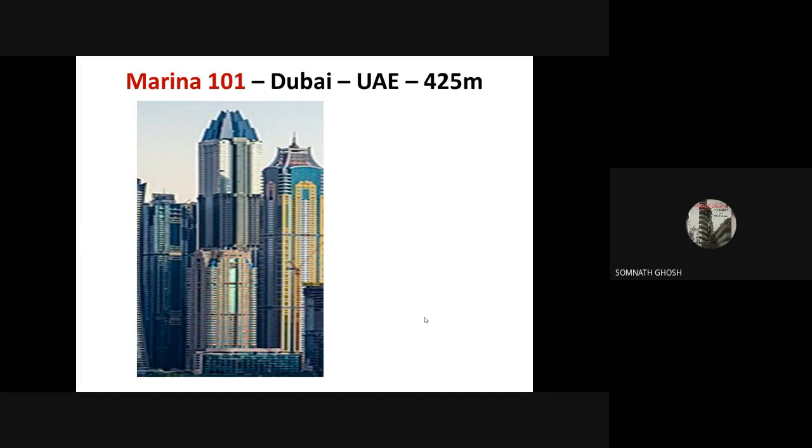If the buildings are very closely spaced, then this kind of interference effect or buffeting effect normally is to be checked, because if you don't check it, then maybe your design is unsafe. Sometimes these kinds of buildings, the buildings which I have shown you in the previous slides, are tested under extreme wind in the wind tunnel.